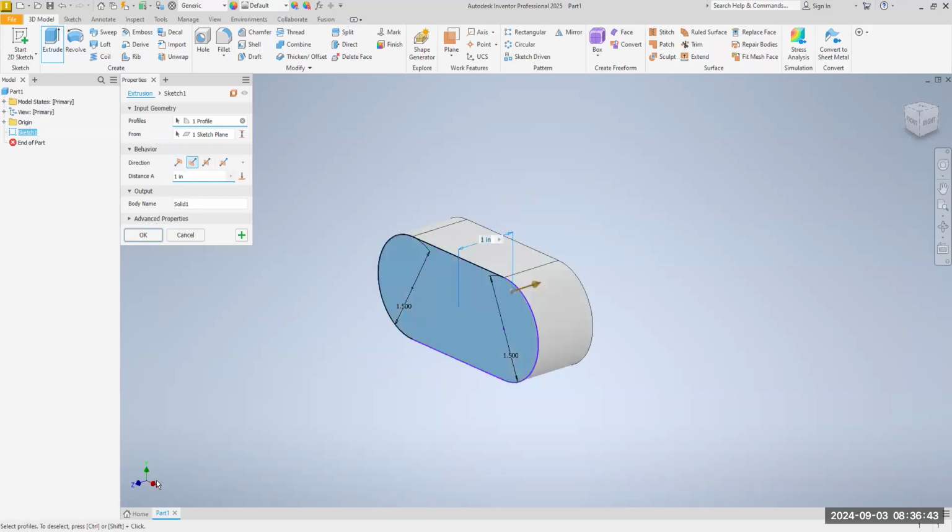Here's why. If you look at your axis down here in the lower left-hand corner, you see the z-axis. The z-axis is important here because when you're machining, the tool moves in an up and down direction. That is the z-axis. The top of the workpiece will be z0. So just keep that in mind for right now. I want the top of the workpiece to be z0. And if you look at the axis, that is what it will be.